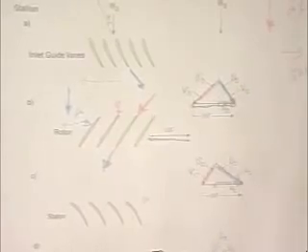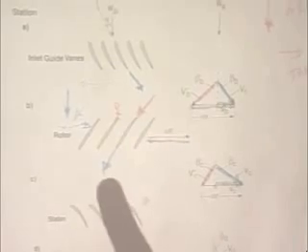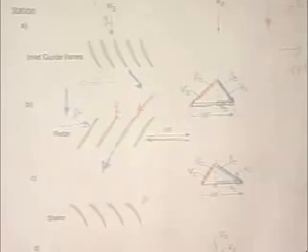I then put myself in the reference frame of the moving blade by subtracting its velocity, and that gives me the red vector, which the person on the blade would see. I then say, well, the flow will always leave this blade attached to the blade at the trailing edge angle. So that blue vector then, which I should have drawn as red here in the relative frame, I'll draw it on this one.